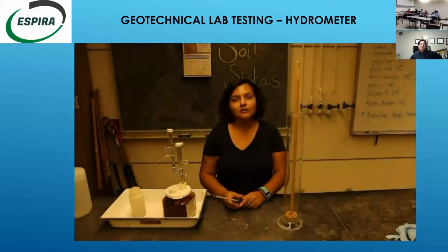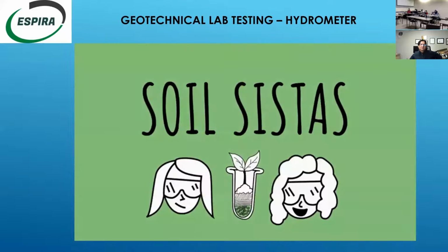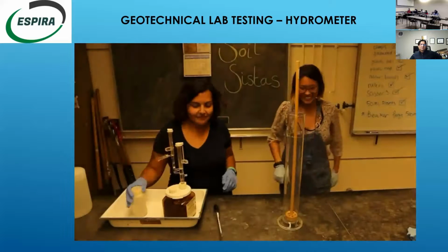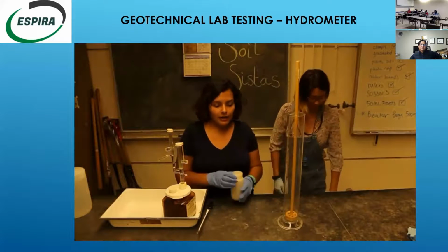So this week we covered particle size distribution, and we used a hydrometer method to determine the texture of our soils. Okay, so what you did in lab this week is that you put 50 grams of soil into this shaking jar, and we added sodium hexametaphosphate.